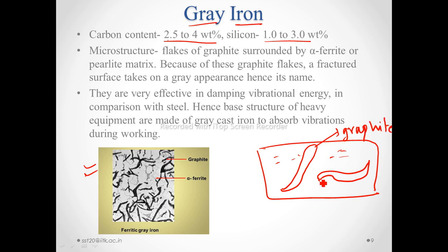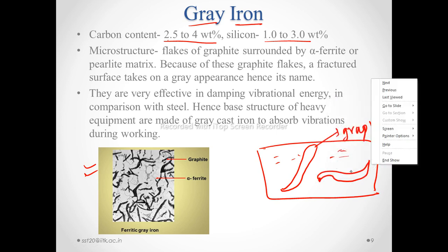These pointed edges act as stress concentrated areas. Due to the structure of this graphite, these gray irons are mechanically comparatively weak and they are brittle in tension.